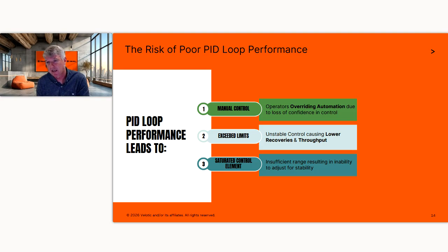Sometimes you don't know that at the beginning, but as your process changes, you notice that you've actually got to change it. If I don't have a big enough heater, even if I turn it on 100%, I'm still not able to get to the new set point in the oven quick enough. If I don't have a big enough exhaust fan, I can't get there. If I don't have a big enough pump, there's no way I can keep that flow rate going, given the diameter of my pipes. So being able to look for things like that tells you that you don't have the right equipment for your PID loops.